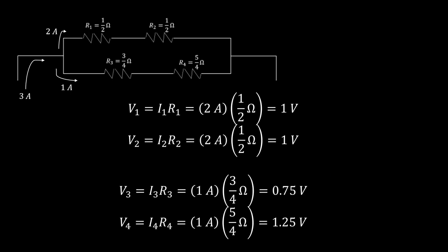Here's what's nice. Path 1 and 2, they were really just a couple of series resistors. And we just determined that through all of path 1, we have 2 amps flowing. Because these 2 resistors are in series, 2 amps is flowing through R1 and flowing through resistor 2. Similarly, 1 amp is going to be flowing through all series resistors along this bottom path. Therefore, we now have all the information we need to solve the remainder of our problem.